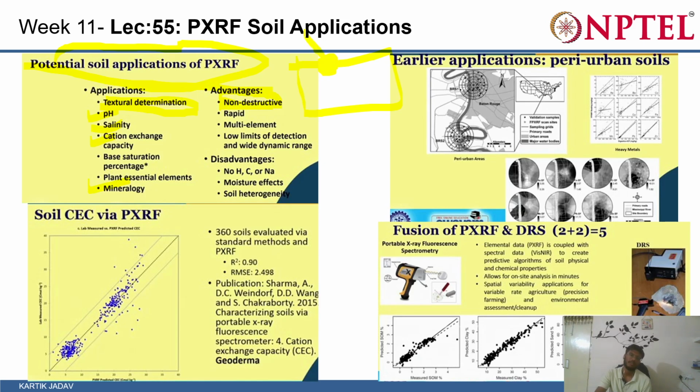taking soil samples from one location. So we are using certain augers or cores to get that sample, and that sample we are transferring to the laboratory. Then we are adding certain preservatives to preserve the targeted contaminants if we are not doing analysis immediately.